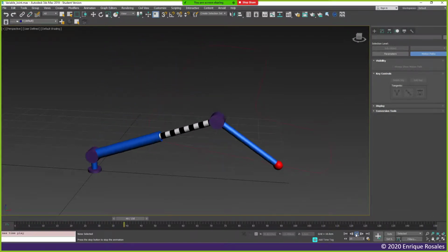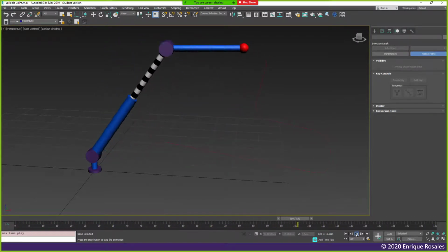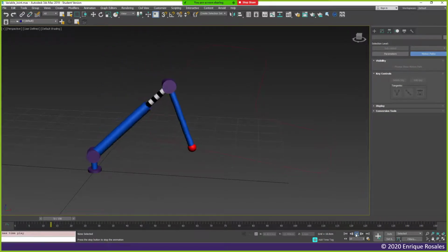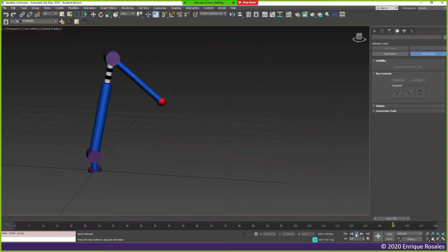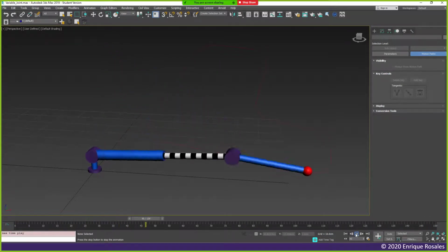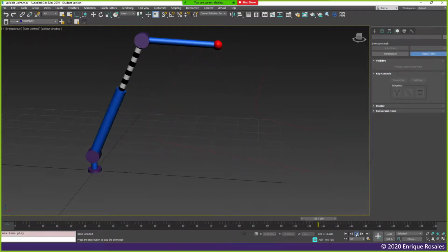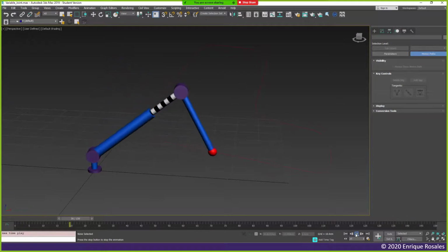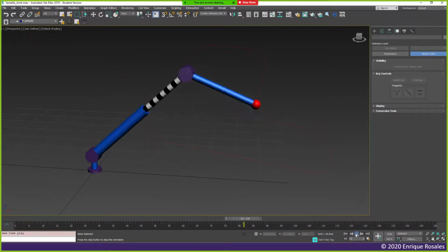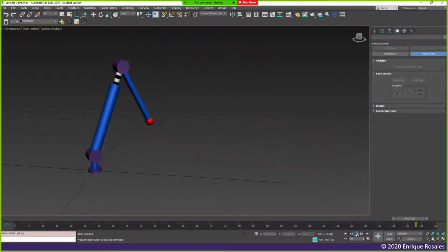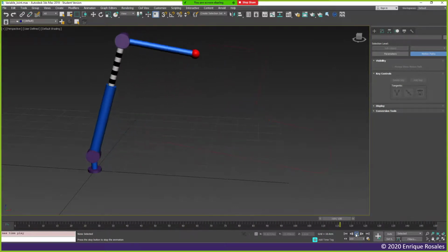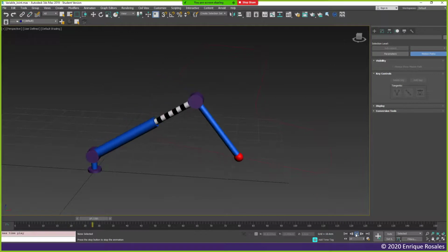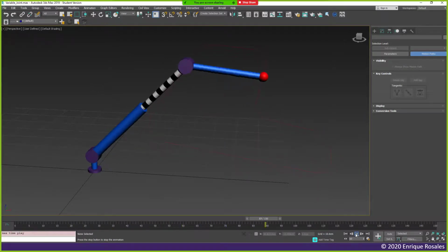The way you compute this is using basically the same principle. You need to just compute the intersection between two circles. The only difference is that the radius of one of those links is not fixed, right? So you can define how much that radius can contract or extend depending on how far is the end effector.